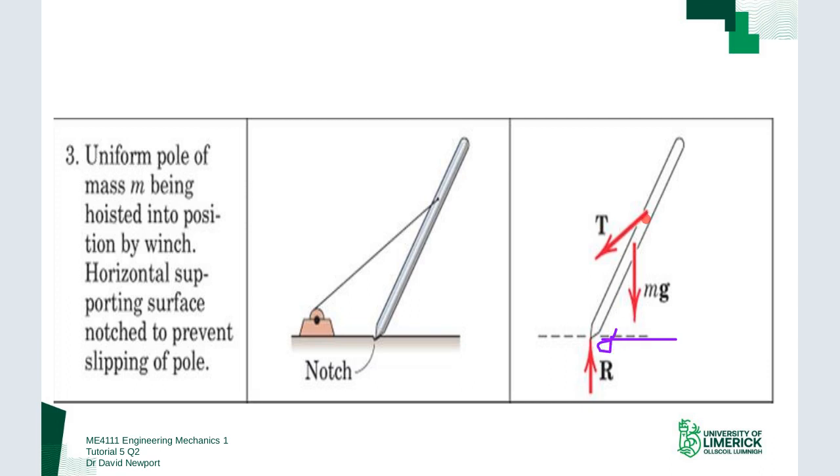But I'm missing one in this direction here. If I look at the figures, this one will have a horizontal component and a vertical one. So in fact, it's going that way. But again, I could have left it the way I drew it originally, and I get a negative for my answer, which tells me I had it pointed the wrong way in the free body diagram.